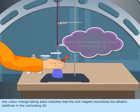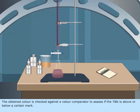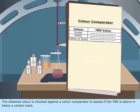Any color change taking place indicates that the acid reagent neutralizes the alkaline additives in the lubricating oil. The obtained color is checked against a color comparator to assess if the TBN is above or below a certain mark.